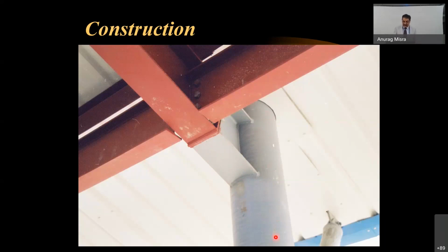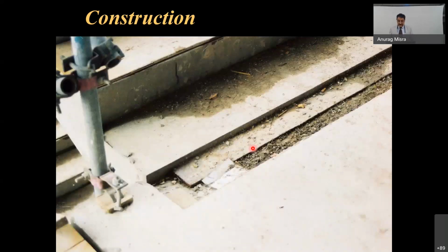So if you are using a circular section for whatever reason, if the architect is saying so, or for economical purposes, you do that, and then the connection could be like that, and then you have the cross bracings for supporting your roofing system. So sometimes I have seen that in this specification, they would prohibit making a bolted connection at the column level. So you just avoid that bolted connection there. You take it slightly away from the columns.